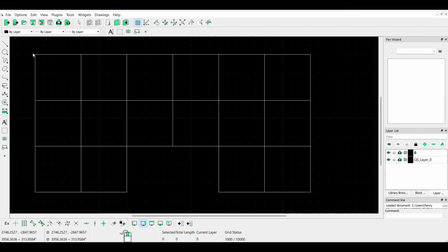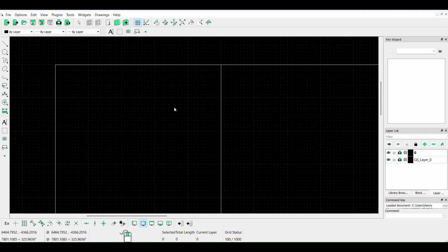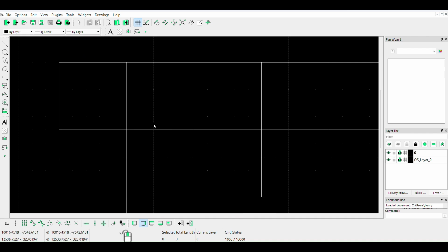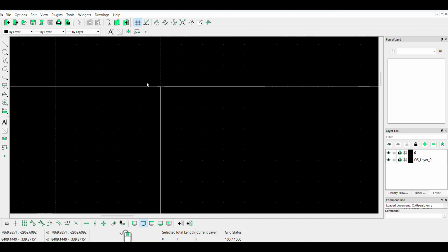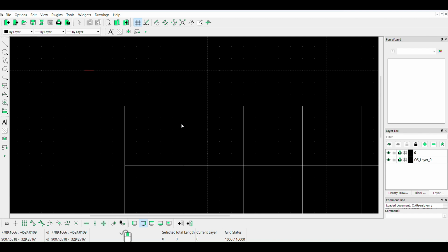And again, in AutoCAD, you need to make sure that all the rectangles are connected. I don't know how you can achieve that, but it's very, very important. Make sure they are all connected. Because even if you zoom in and have a 5mm gap between the panels, the software will treat it as an expansion joint, because in the software there is room for expansion joints.